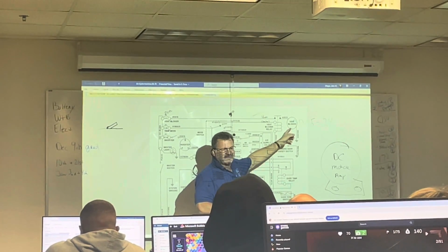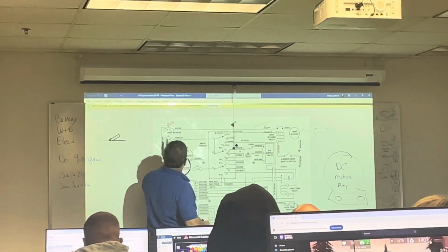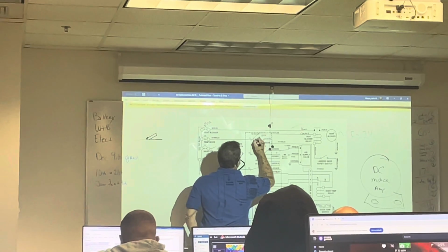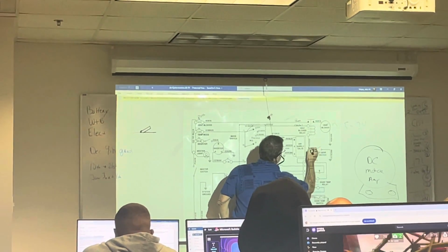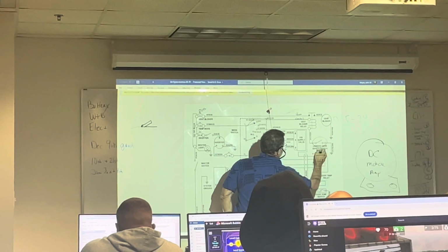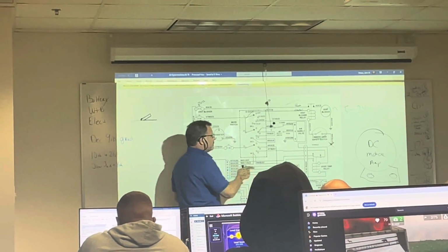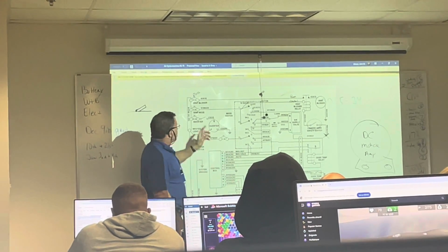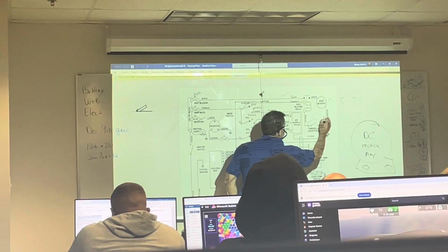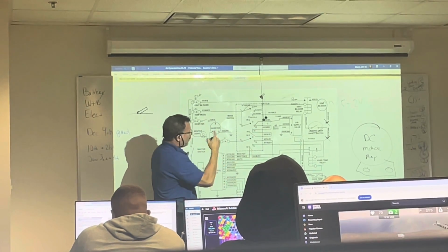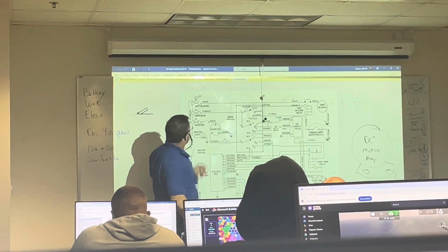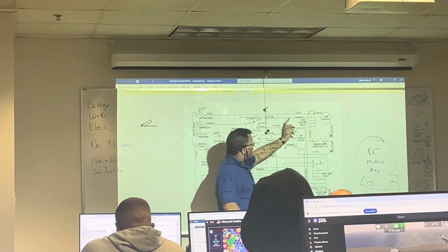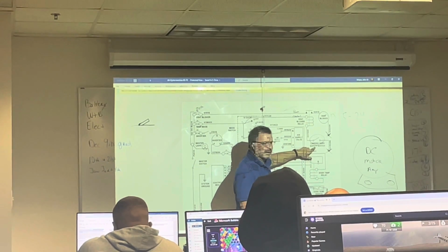So I want this vent blower to work. In the cockpit, coming through my control circuit, it comes over here, I meet that, comes over, it's standing by, but there's something where I can't get the ground. The first thing when you troubleshoot, you need to find your power, find your ground for the particular circuit you're looking at. So I have a ground, and then I'm going to have a ground for the motor. So these two guys here, I've got to get to. Well, how do I get to them? You get to it because when you hit your control switch in the cockpit, and we select that, then it gives me my power, everything's good, except right here.